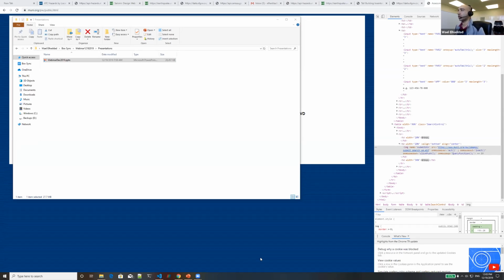So many times, at least for the purpose of regional simulations, what we do is we use mapping schemes or mapping rules. We use some rules to map the building occupancy, the year it was built, and maybe the number of stories to a particular structure type or structure system. And in our tools for regional workflows, we treat this as an uncertainty. If you're doing a regional simulation for so many buildings, you will definitely end up with some uncertainty. You will not know for sure. So one way to handle this is to assume this is an uncertainty in the input.